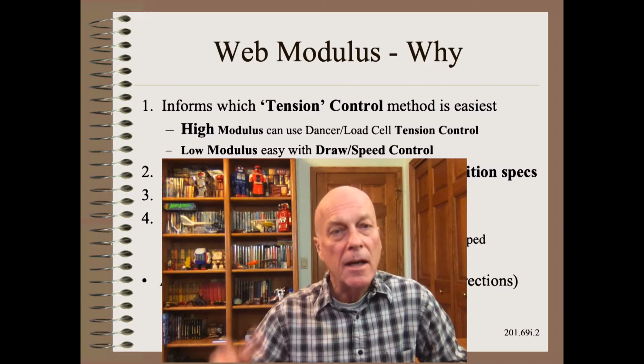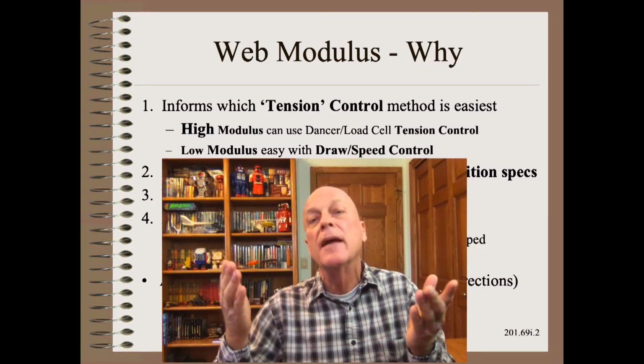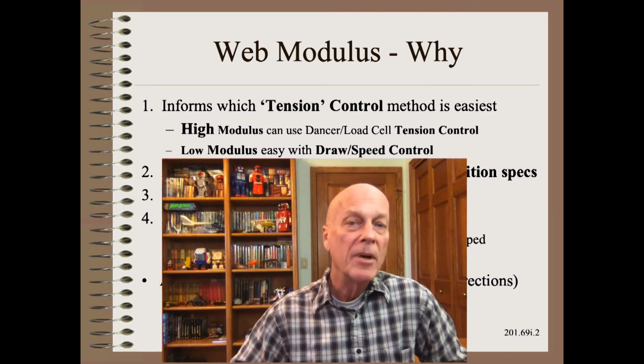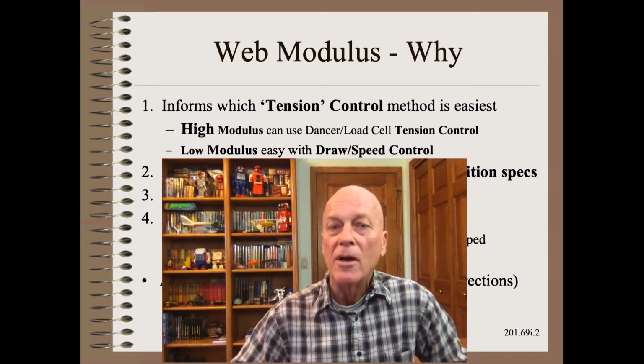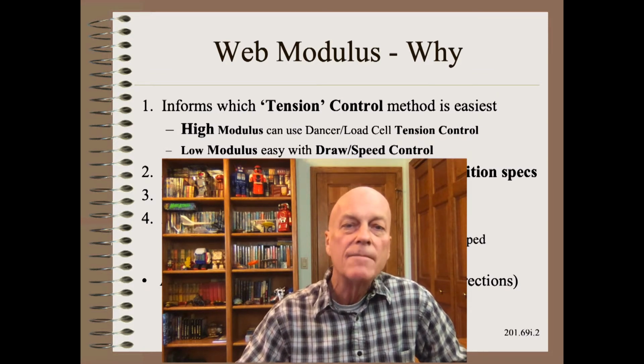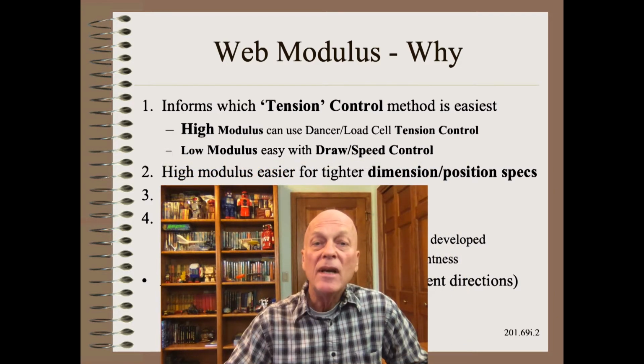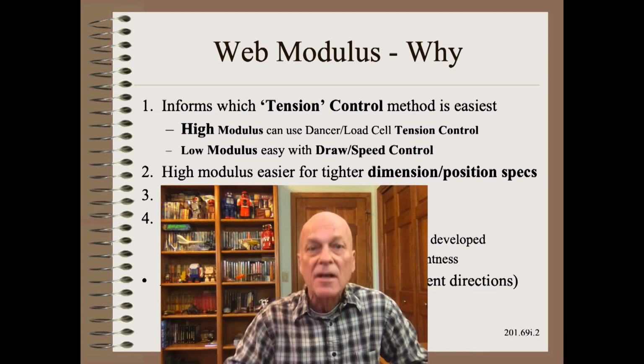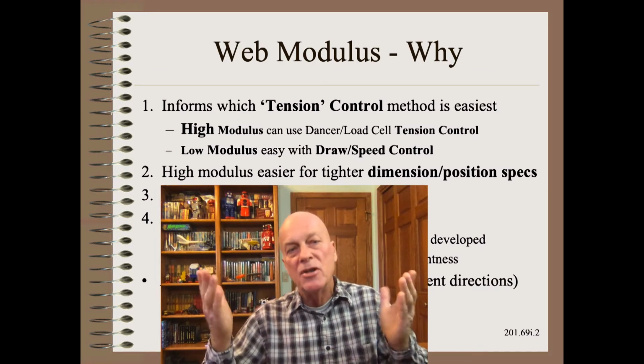Low modulus, on the other hand, can go either dancer or tension or draw control. The latter being more common because it is an easier drive control method, albeit more confusing for everyone else besides drive programmers.